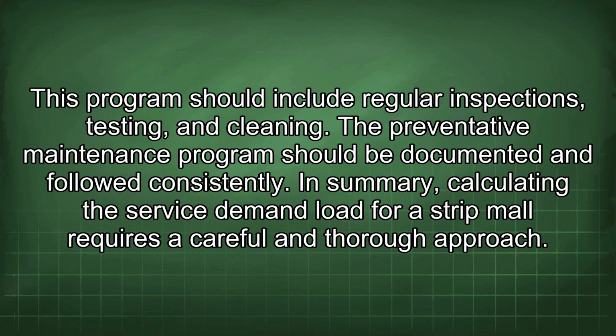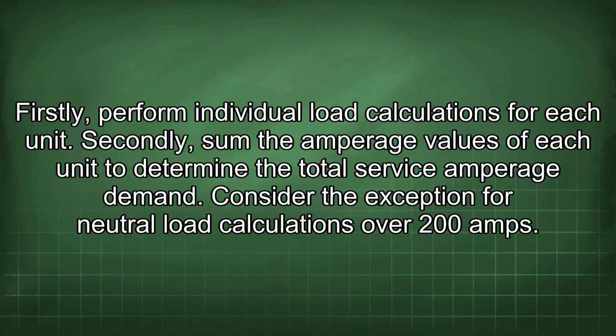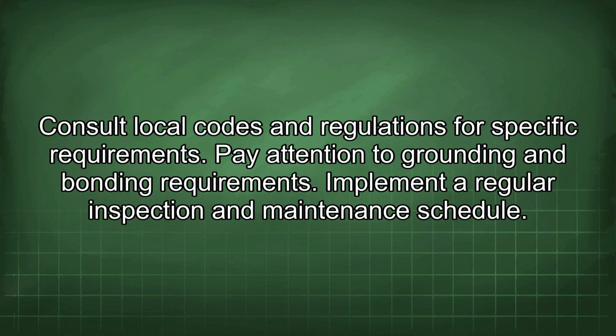In summary, calculating the service demand load for a strip mall requires a careful and thorough approach. Firstly, perform individual load calculations for each unit. Secondly, sum the amperage values of each unit to determine the total service amperage demand. Consider the exception for neutral load calculations over 200 amps. Consult local codes and regulations for specific requirements.